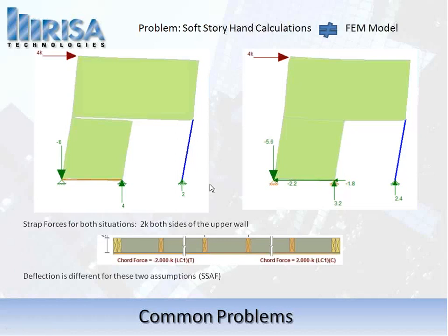The other issue is that if you really were thinking of it as this left portion and we tried to model it that way to match a hand calc method, the deflection goes haywire. You can see it's sort of letting go. Even if we just look at it visually, we can see how it's deflecting a lot differently from this model here. And it's probably not a really good assumption to let these 2 plate models veer away from each other or separate like that.